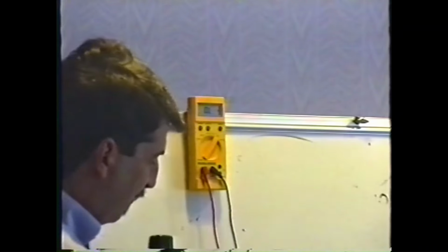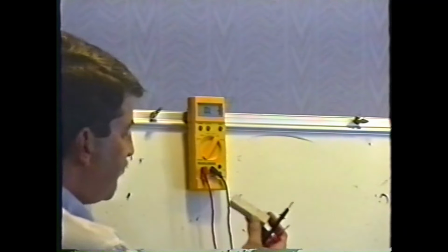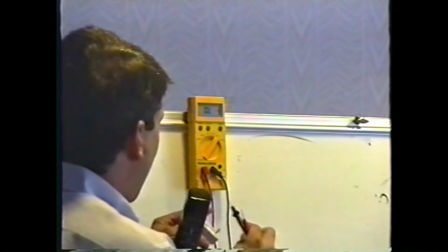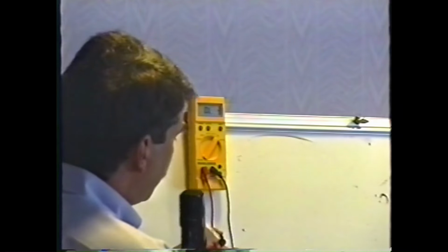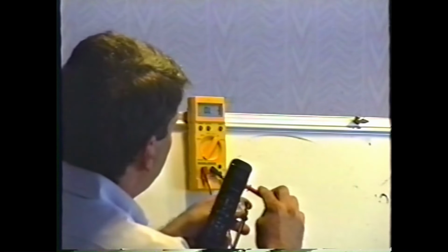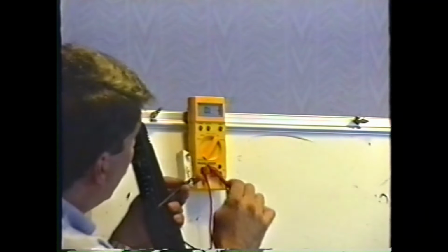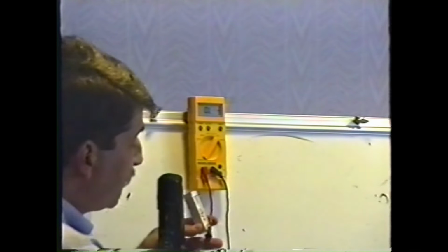This one also says open on the bottom. But obviously, I wrote that on there. This one, this is a humongous resistor. This is an 80-watt resistor, gigantic thing. 330 ohms, 80 watts. When I put my meter leads across it, nada, nothing. The meter shows me nothing. Well, it doesn't show me no ohms. It shows me infinite ohms. It doesn't change at all. Obviously, open resistor. So this is what resistors do when they fail, is they open circuit.